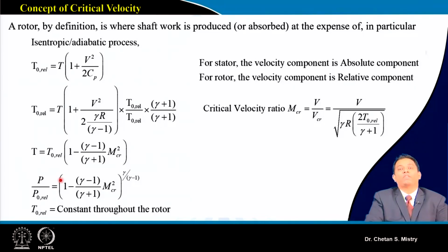Today, what we have discussed is the introduction of critical Mach number, and as we have discussed, we will be using this critical Mach number for defining the local Mach number at a particular station in our compressor. This can also be used for defining the local Mach number for turbines.